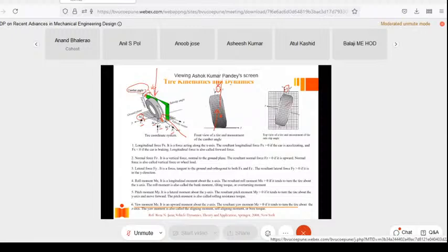So this is called slip angle, and slip angle basically defines the lateral forces and the aligning torque. So in principle you have longitudinal force, normal force, lateral force, rolling moment, pitch moment, and yaw moment. But these are called the overturning moment, rolling resistance, and aligning moment in the tire coordinate space.